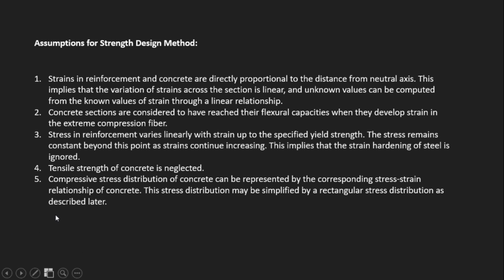And number 5 assumption, the compressive stress distribution of concrete can be represented by the corresponding stress-strain relationship of concrete. This stress distribution may be simplified by rectangular stress distribution as described later. So mamaya ipapakita ko yan.